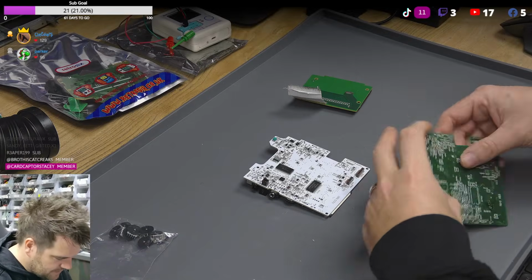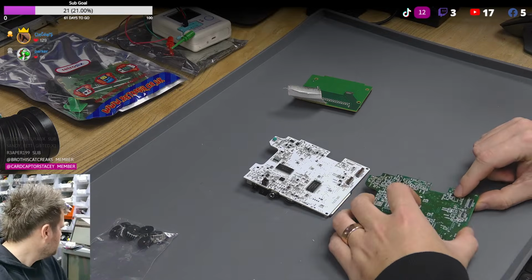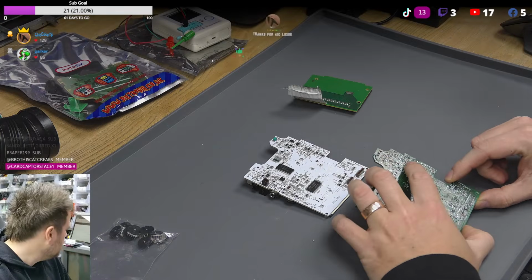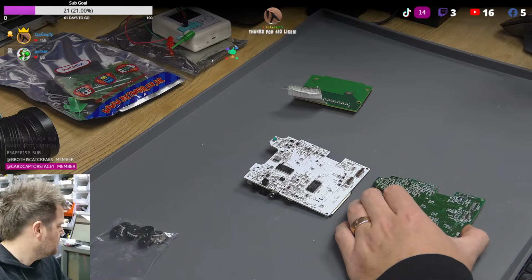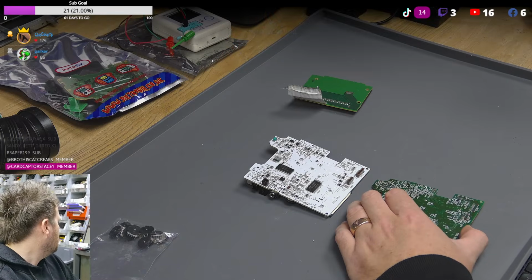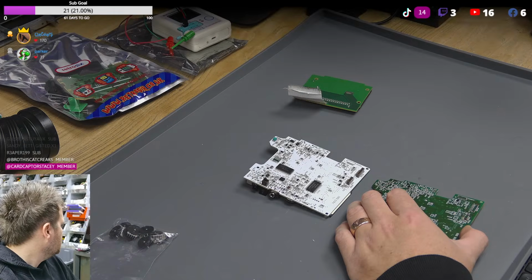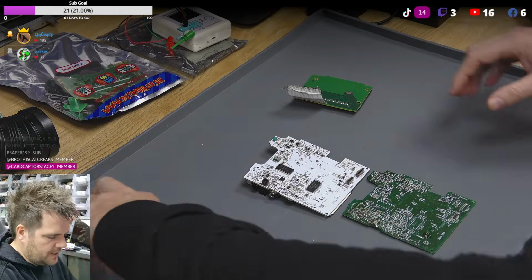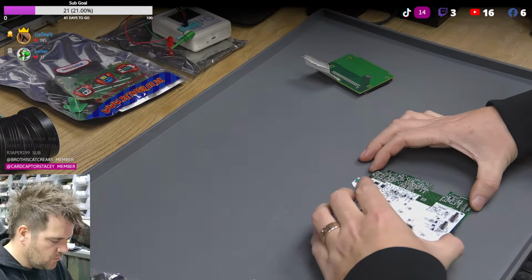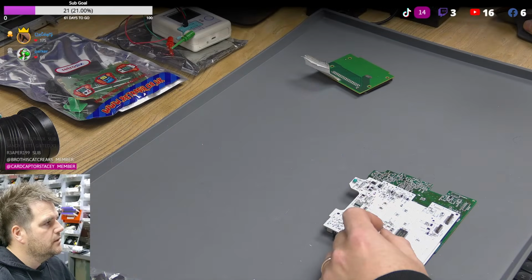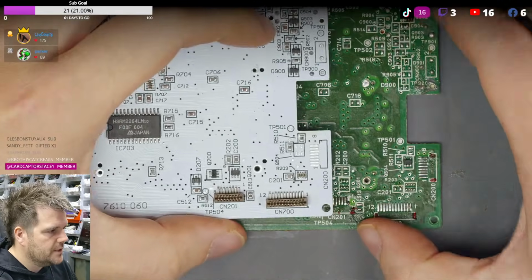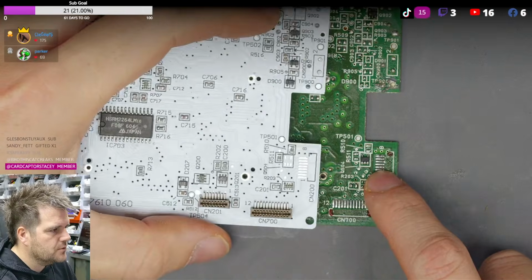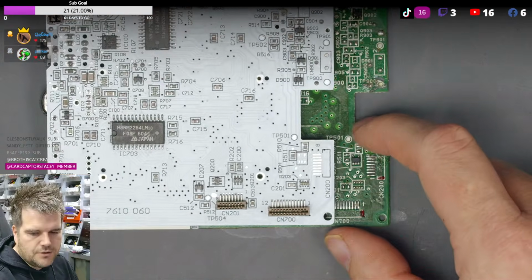Right, so Q504 we've identified. Q902 is blank in there, and Q503 is blank. So the Excel sheet's also fine. That's got everything written down that we know of, and we basically have 3 chips we don't know of yet. So let's get to some work. We'll go to the overhead. We'll pull focus. So what we want to do is transfer the remaining parts over. So we'll transfer this little Q504 over.